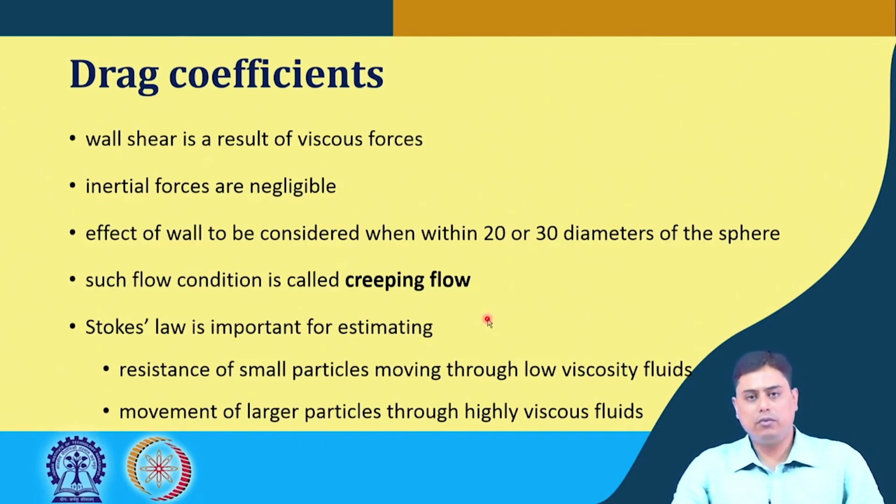Otherwise, we can say it is an infinite pool with respect to the particle diameter d. If the walls are separated by more than 30 d or 20 d, we can say it is an infinite pool of liquid with respect to that particle, and then Stokes' law is typically applicable. If not, the effect of the wall has to be considered, and certain modifications need to be made in Stokes' law to calculate the drag force on the particle.